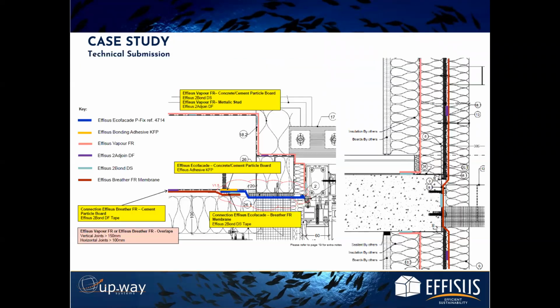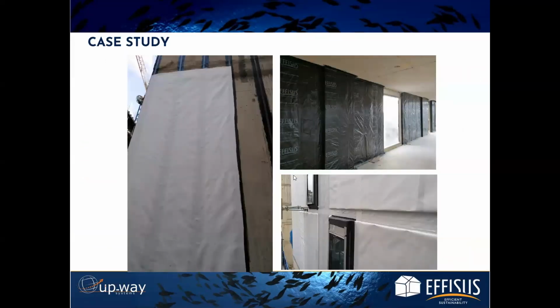And here, of course, we have a very simple technical submission, one of the many technical submissions we have done for this project. And here, of course, we explained exactly where to place the membrane, how to seal the membrane with this specific substrate. Here is the concrete substrate. For instance, here on the external breather membrane, how to deal with the perforations, how we should deal with these specific perforations here. And so this is all we do here at our company. And this is, for me, very important to mitigate future errors and future mistakes when people are applying the products at site.